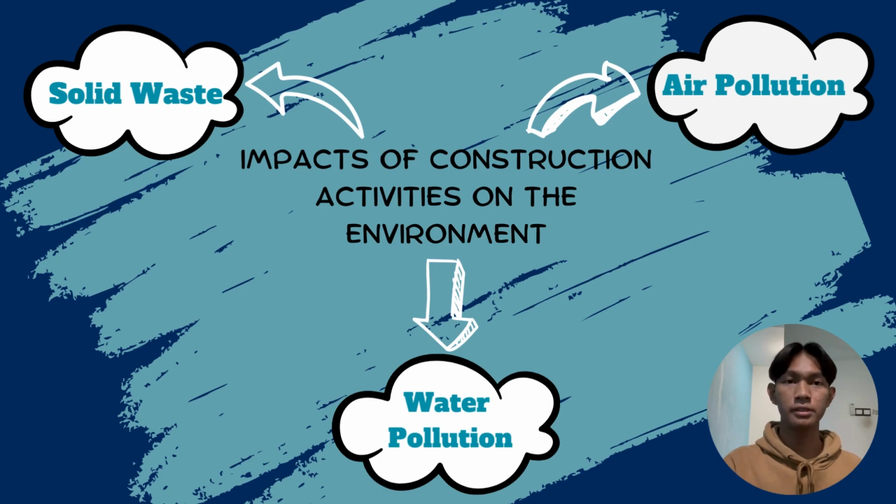Construction activities can harm water quality by introducing pollutants into water bodies. The improper disposal of concrete waste and washout from concrete trucks, which can contain high pH water and chemical additives, is a common cause of water pollution during construction. This can harm aquatic life and negatively affect overall water quality.